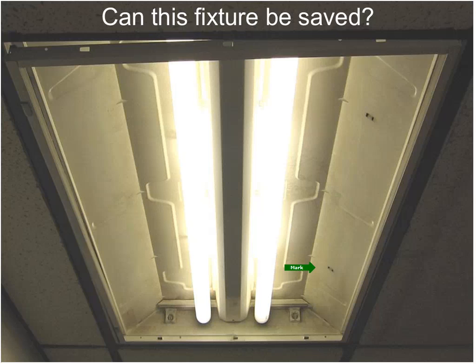Pretty obvious here, we don't have a lens. It's gone. And the upper corner here, maybe one of these latches is not working. It isn't closing all the way. A lot of these are plastic and they break off. So what would you do? Maybe we retrofit this. You could put a new lens in here, a new kit, maybe go to LED. So we've got some options here.